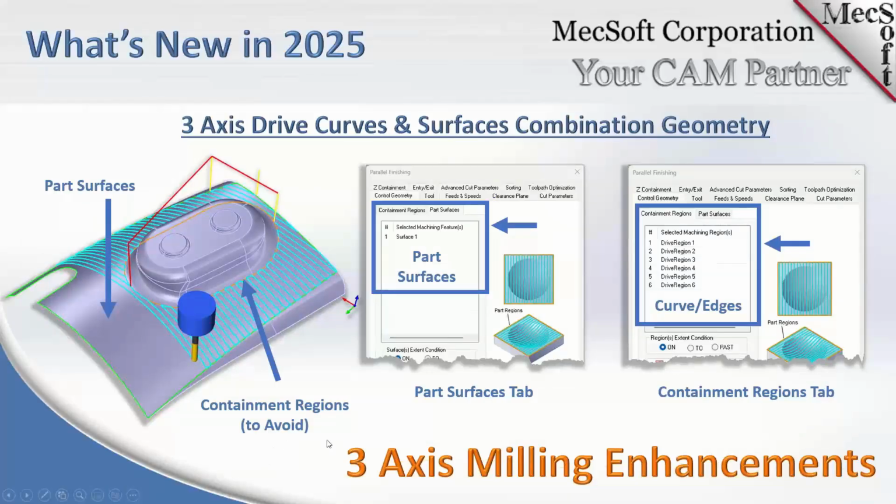Okay, here's an interesting one. In 3-axis, we provided the ability to use both surfaces and curved regions. And when you do that, similar to 2-axis operations where you have a nesting perimeter, like an outer perimeter and an inner perimeter, the toolpath is actually between the two. If you look at the picture over here, we're selecting one part surface in the part surfaces tab, and this is parallel finishing, 3-axis.